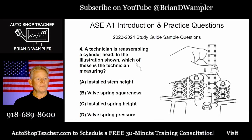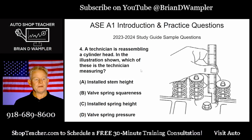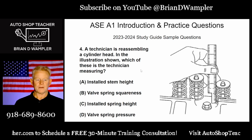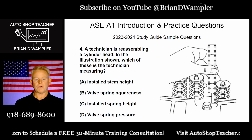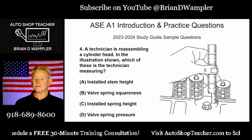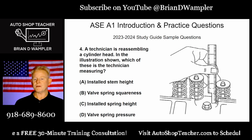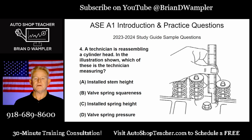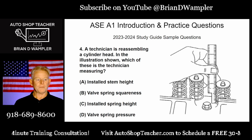Okay, so what is this technician measuring? Is he measuring the installed stem height? Okay, the valve stem installed height. Is he measuring valve spring squareness? Whether the coils of this spring have gotten wonky, or whether they're still in a nice circular row from top to bottom.